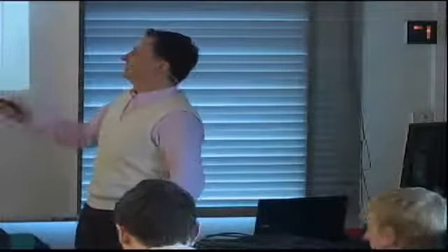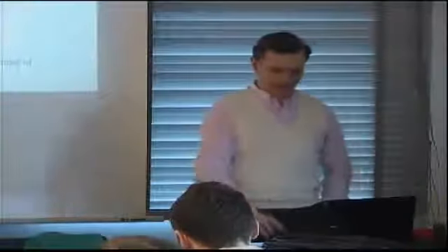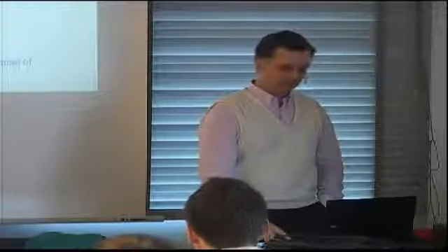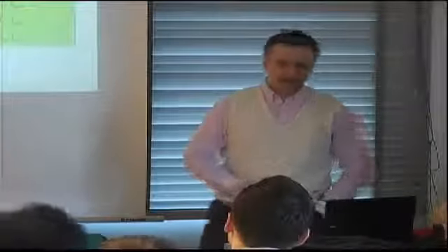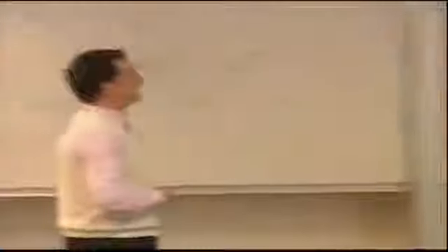I can tell you up front now, typically if you only have 2 stiffeners at the 2 ends, this is not a good approximation. But in general, with more than 4 stiffeners, you are fine. And that's, again, based on experience. It's not guaranteed to be good enough. So let's start calculating, and we'll continue on Friday.